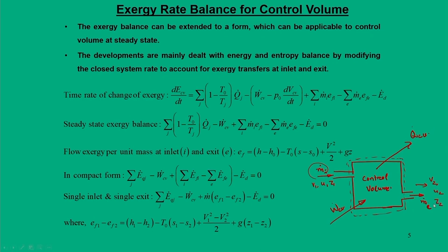So, all these possible terms can be included, and apart from that, when you do the analysis of exergy, we need to think about the surroundings or environment, and this environment condition is normally referred to as P naught 1 bar, T naught 300 Kelvin.